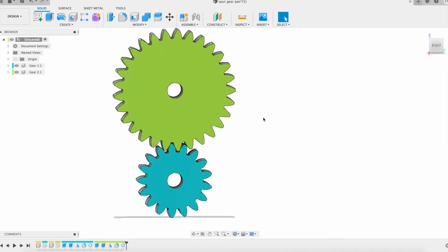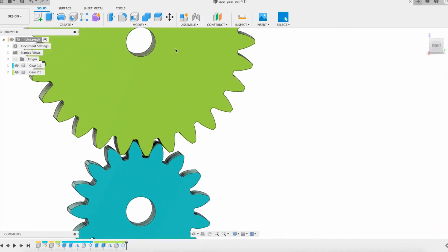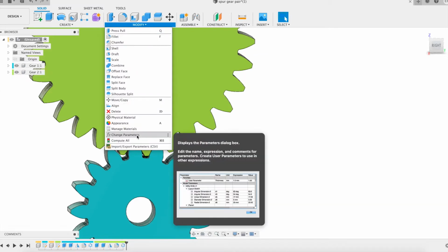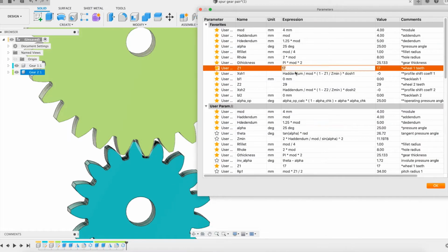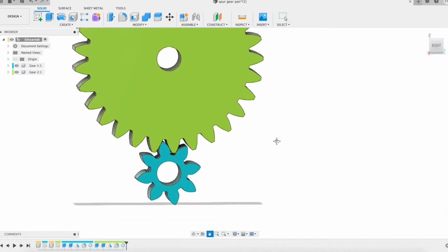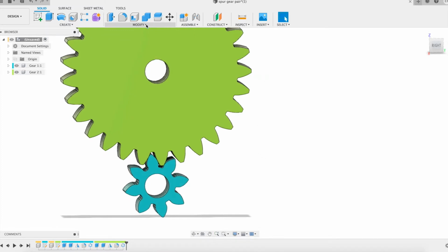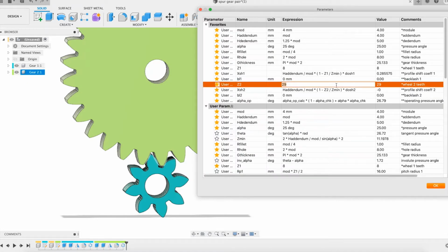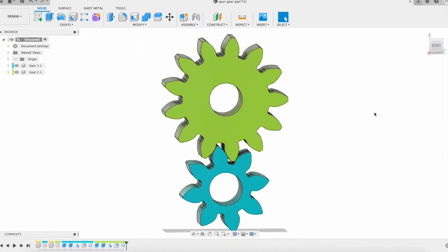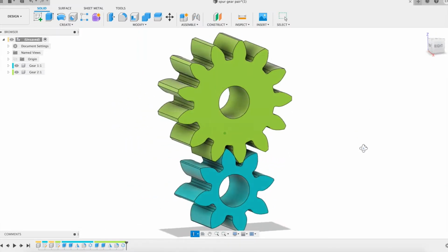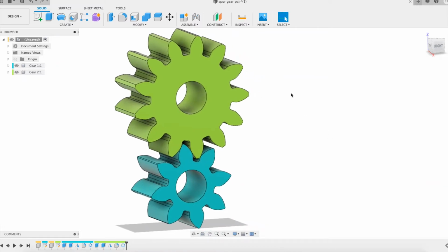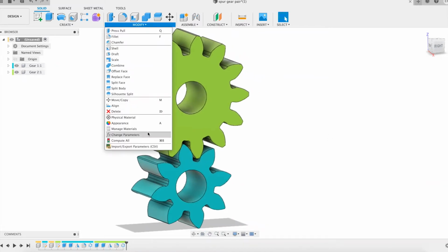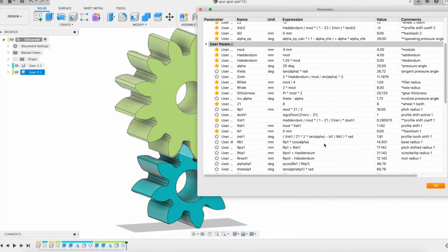At the end of that previous presentation I had changed the number of teeth of one of the wheels into a small number. This wheel could then be called a pinion. It turns out that pinions usually need to undergo a tooth profile shift in order to mesh properly. This profile shift requires an adjustment of the center distance between the pinion and the ring with which it is to be meshed. The difficulty lies in the calculation of the center distance because it does not depend only on the pinion that has undergone the profile shift, it depends on the pinion ring pair constituting the gearing as a whole. One of the parameters that must be calculated to determine the center distance is the operating pressure angle.